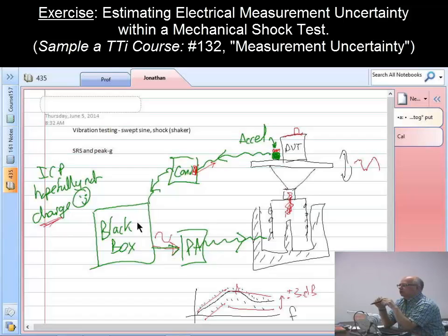But if we're looking at impulsive or tailored pulsing going in, there are techniques where we can take the pulse that we want, strip the phase so all the components are in phase, then put that pulse out, and that gives us the worst possible shock for that phase. Right now it's just slipped my mind what we call that. But essentially at that stage we say what's the worst possible case we could have for these frequency components, stripped phase.